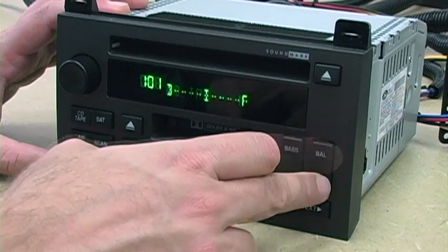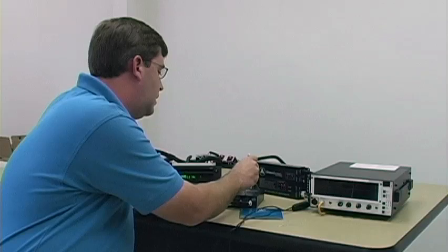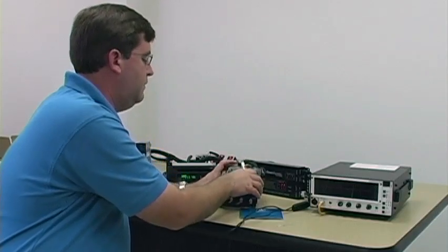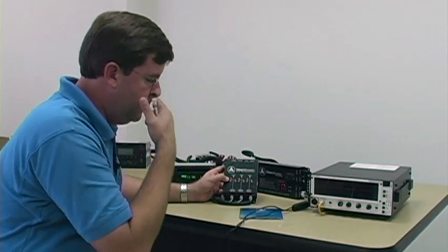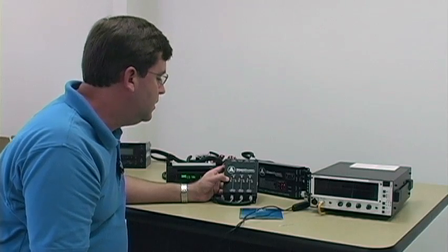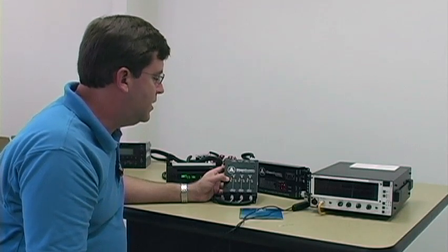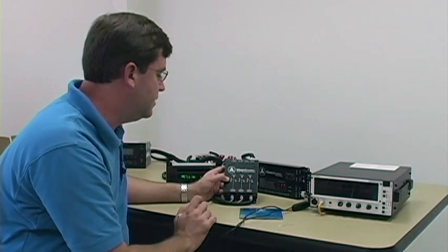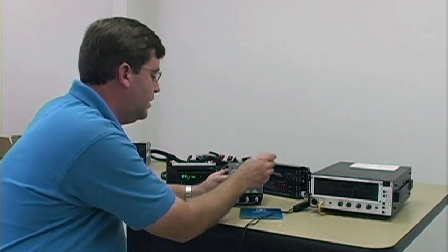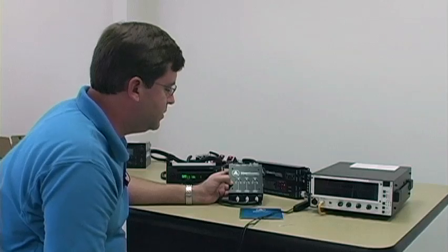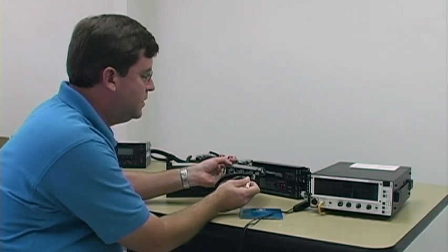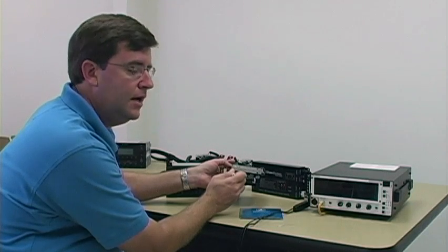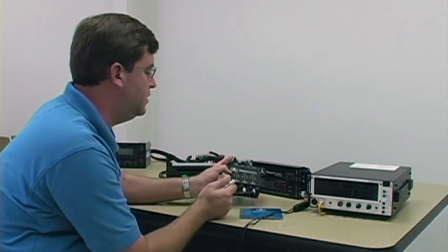And then we're going to need to set the input levels on each of these bands so that we have a good, even summing result. And this is how this is done without the need for any external tools. This is the real killer feature of this product, is its ability to tell you the relative level of signals. Now I've turned all these potentiometers all the way down. I've got my 3 inputs plugged in. I've set the range switches on speaker level. There's a range switch on each input that's either speaker or line level. We'll start with the speaker level position on each one.